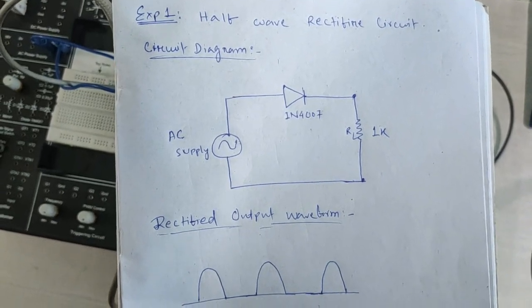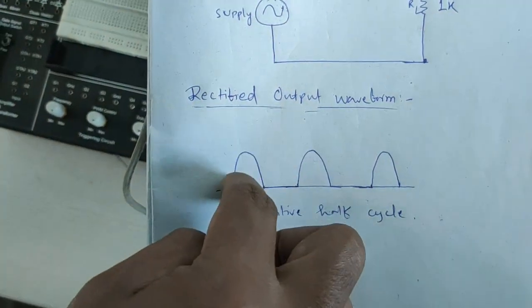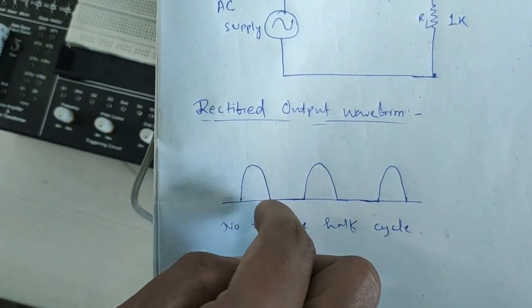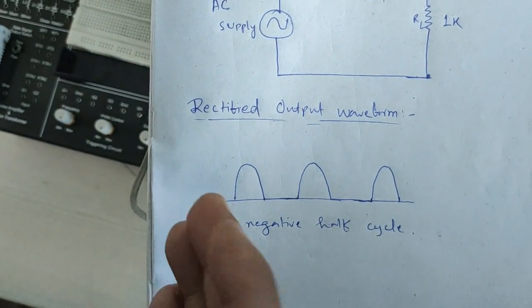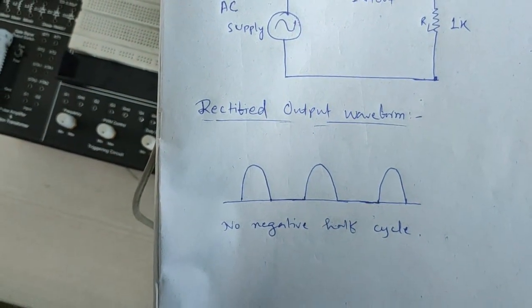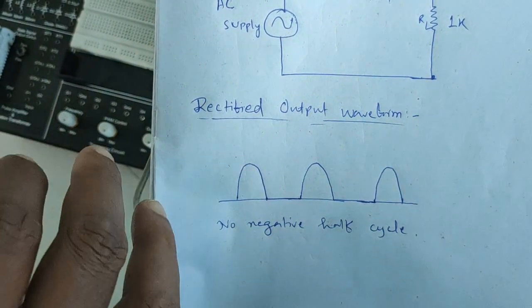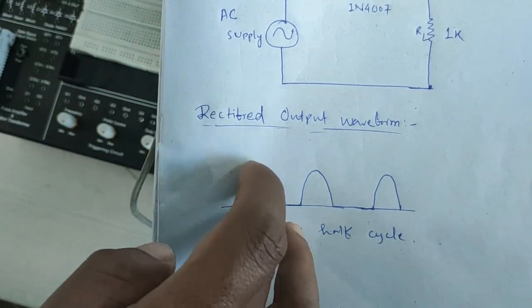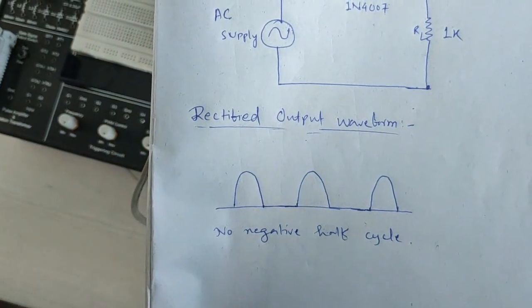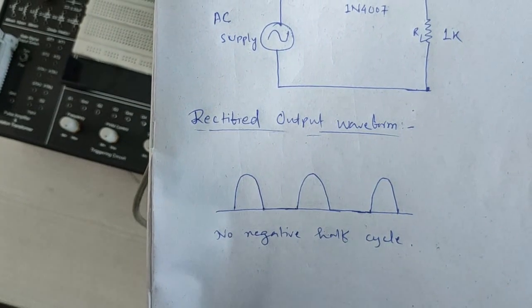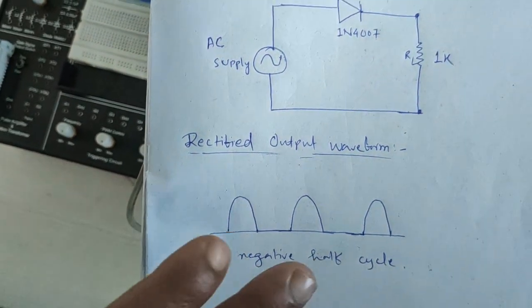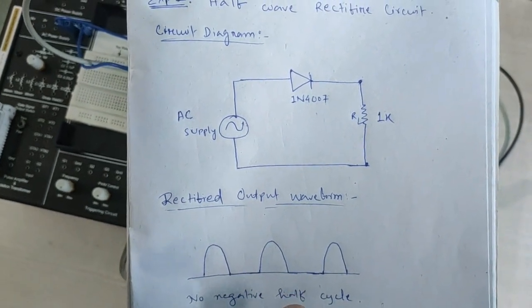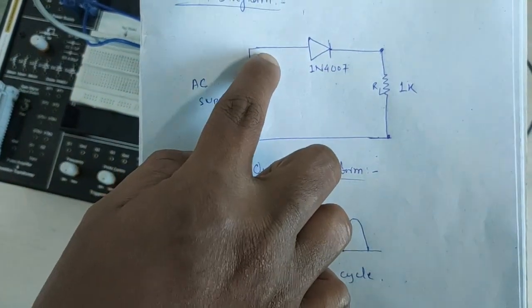In a half wave rectifier, actually one half of each AC input cycle is rectified, right? When the PN junction diode is in forward bias, it gives a little resistance, and when it is in reverse bias, it provides a higher resistance. So while it is in forward bias, in the positive half cycle we will get an output current, right? The input has both positive and negative half cycles, but during the positive half cycle the current will flow from positive to negative, right?